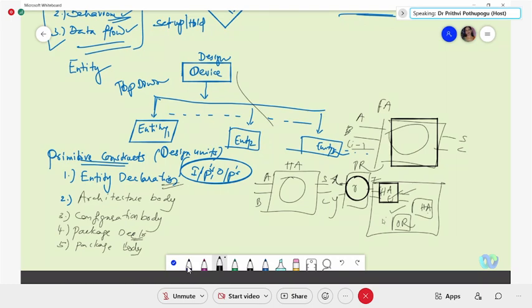You said OR gate, inputs, outputs, we were defining. Say if you say this as bit, it can be a vector, the value, say if x, y is there. You say in bit, means it is type input and type of the value is bit, that means single value. If I say it is in vector, means it is input type and it can have vector values, that means 0, 0, 0, 0, 0, 1, some set of values. You can declare them. Okay, that declaration is given in package declaration.